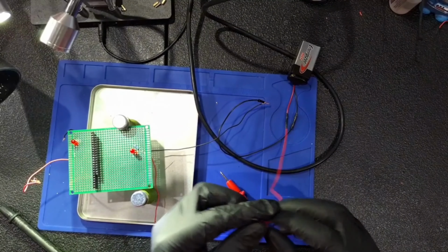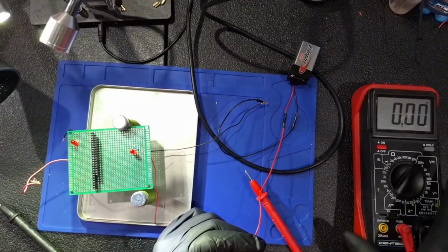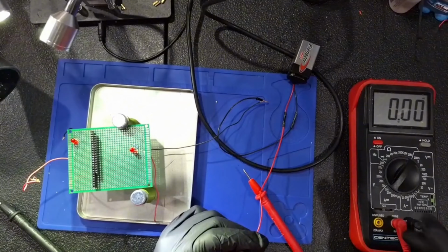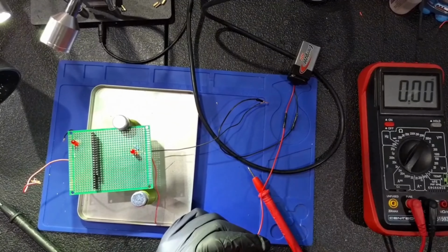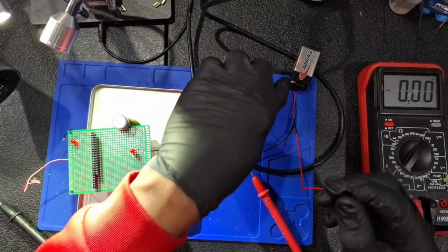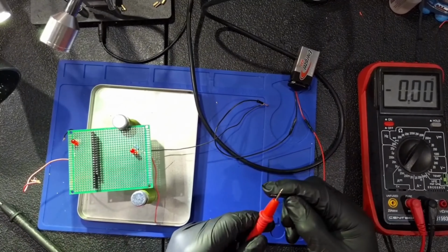Alright, let's go now. So I have the red wire coming from the positive on the battery. I have a multimeter ready. I've just quickly reset it. Connection, red probe is in the milliamps connection. Dial is turned to 20 milliamps. Red connection from the positive, red probe on the multimeter, connect that.